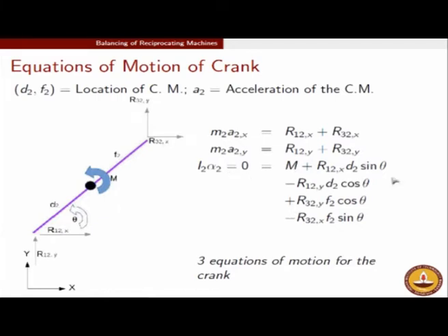If you look at this equation, all the moments taken together is 0. We are trying to ensure, through the application of this moment M, which we call the load torque, that this total summation gives us 0. Fine, R1, R2, R3, all of them could vary, but then the moment could also vary, and together you will have equilibrium.